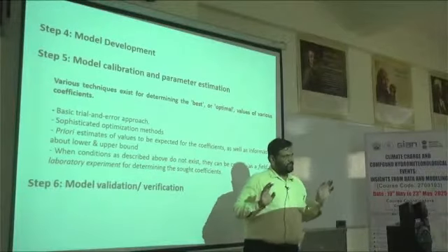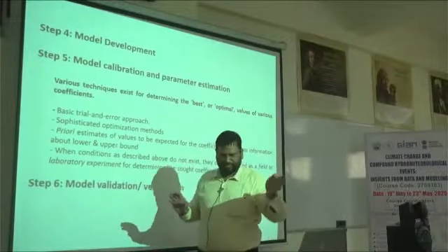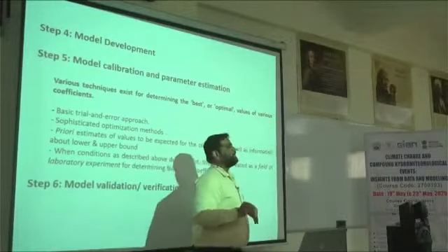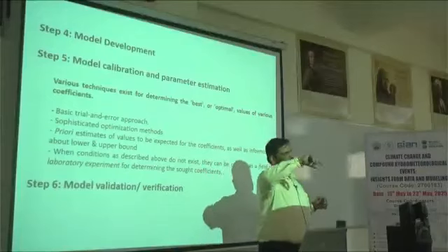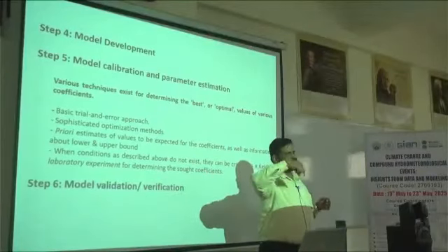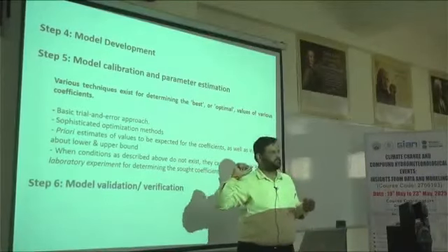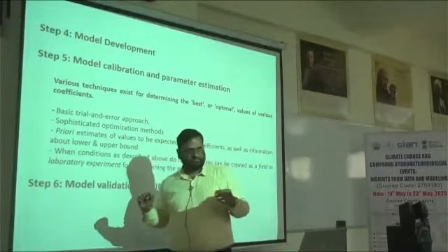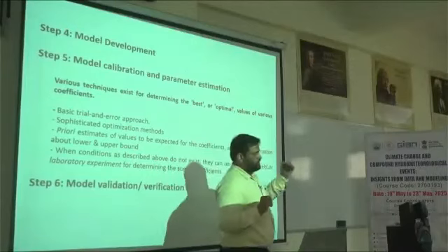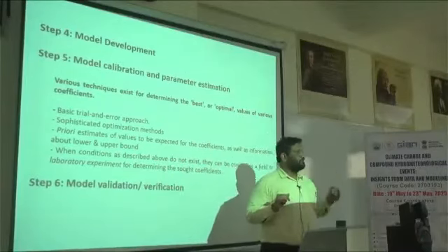So if you have 70, 30, in K. Subramanya, they have given the complete table for the curve number with its possible range as well as the land use type and the soil types also, in the Engineering Hydrology book. Like that we have to understand the groundwater parameters also.